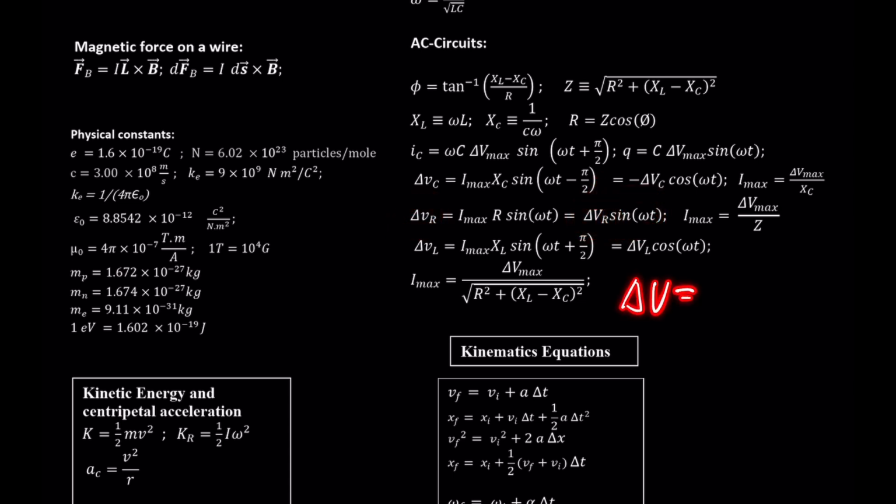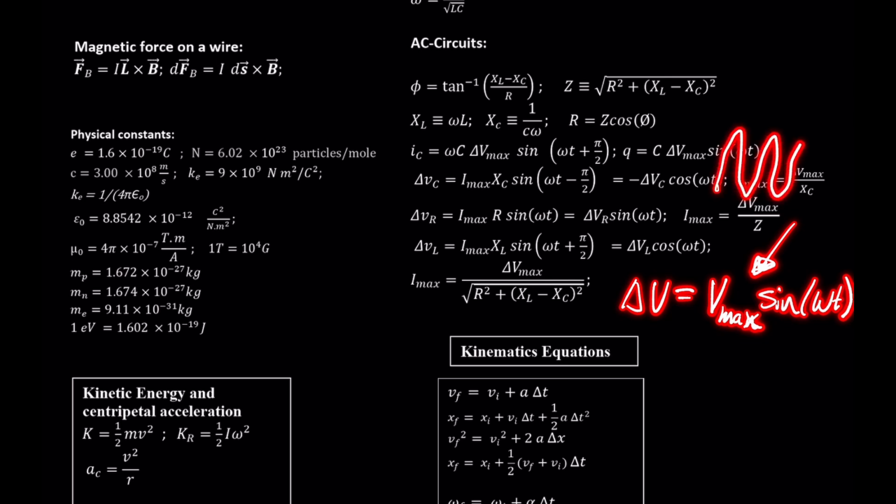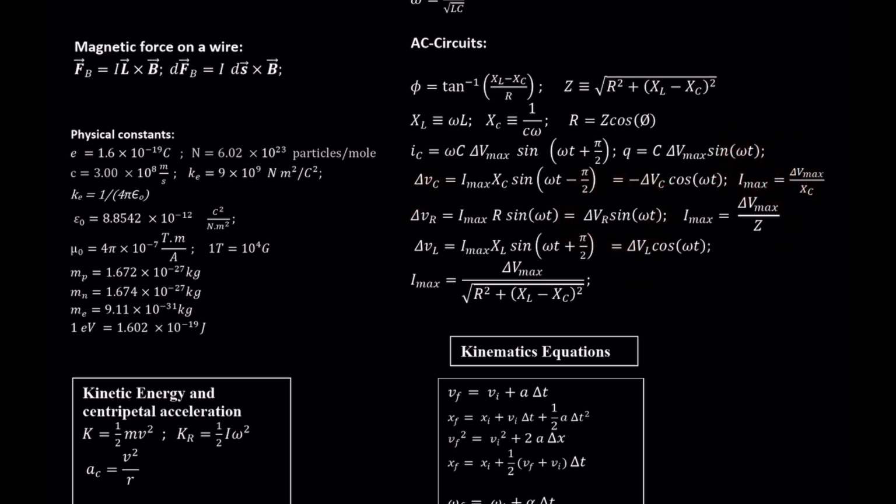And we're assuming the voltage that we're applying is something like this. So in an AC circuit, I produce this voltage, like this is coming from my power supply, a voltage that follows a sine wave like this. I attach a resistor to it, and the voltage on the resistor looks identical to the voltage from my battery supply. Cool. For the capacitor and the inductor, you actually see a slightly different behavior. Cosine and cosine for the inductor and the capacitor, and the capacitor actually has an extra negative sign, which the inductor doesn't have.